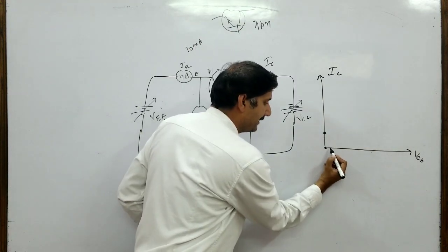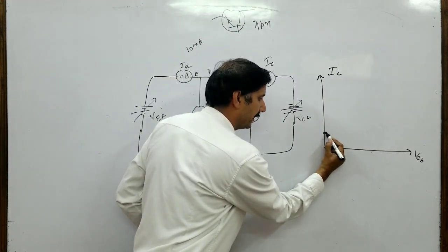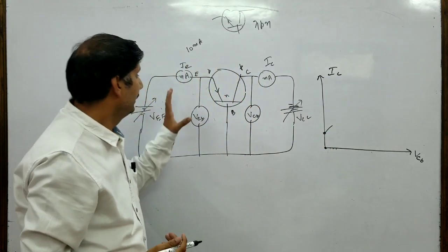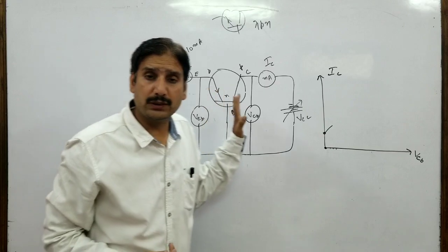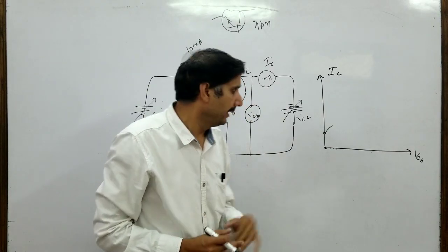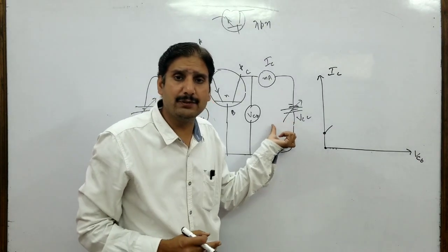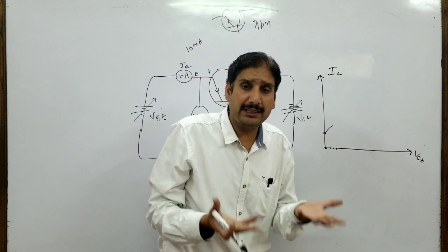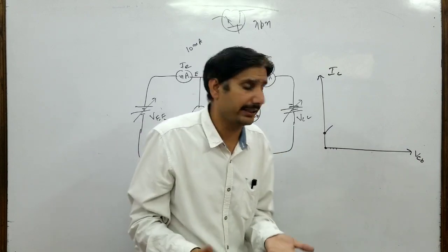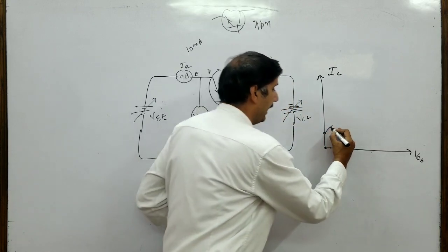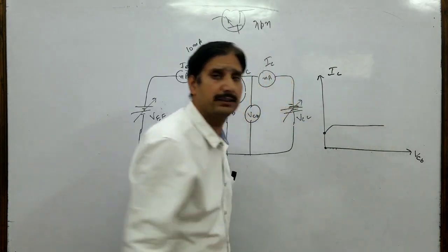So as you apply a slight negative voltage over here, the current will increase. Now what is happening? 100 started their journey, 2 were neutralized in the base region, and the remaining 98 have already reached the collector region. Now even if you keep on increasing the voltage at the collector, that doesn't affect, because all the remaining 98 holes have already come to the collector region. So by increasing the voltage, you won't be able to increase the collector current, and collector current becomes constant.